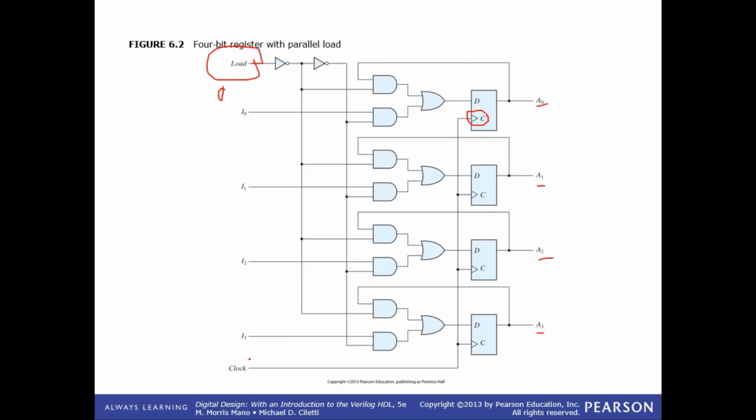So we want the clock to be synchronized and untouched until it reaches the D flip-flops. That is why we add circuitry to the D inputs of our D flip-flops, so that we can hold the outputs through the input D, and we do not change the clock C.